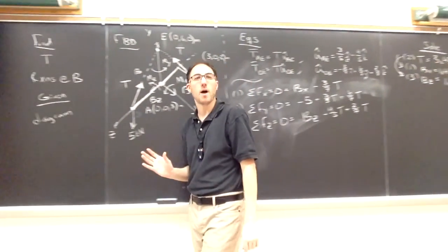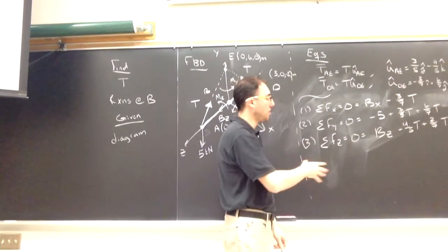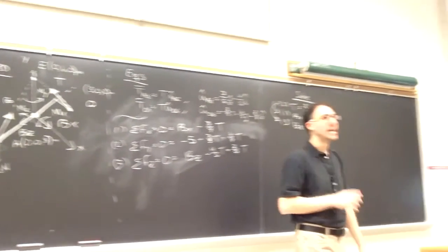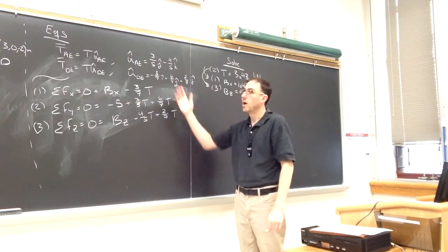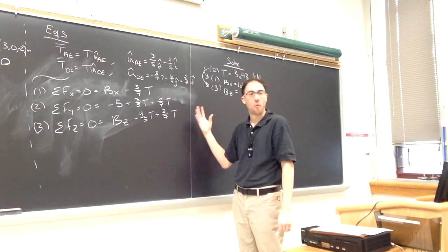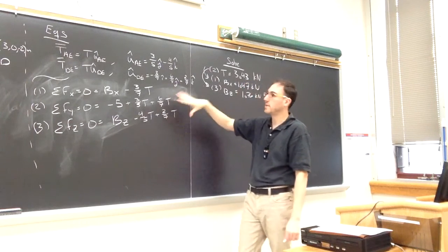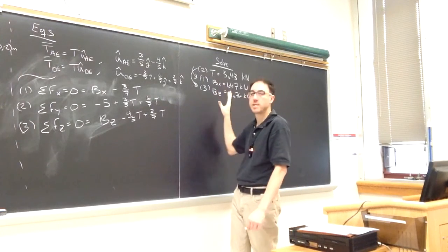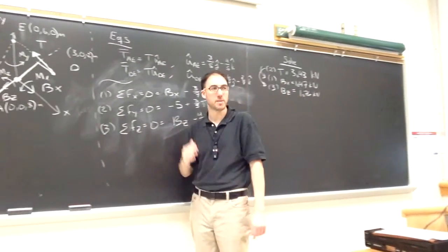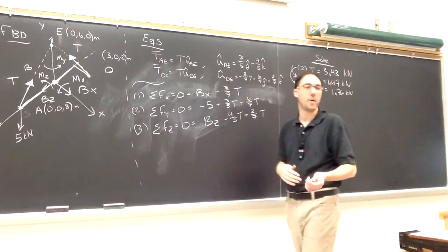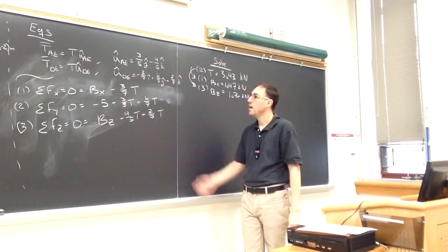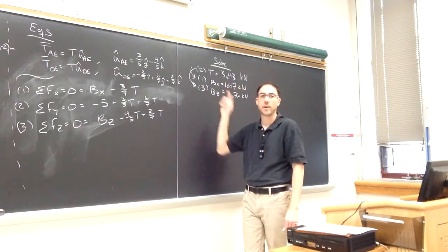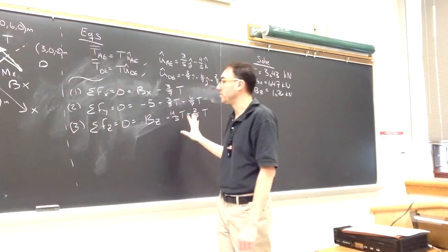For this particular problem, we only had 3 forces, and we were able to solve for all 3 based on the force equations alone. That's not necessarily going to always be the case, because we could have some examples where we have 4 or 5 unknown forces, in which case we might be able to solve for 1, maybe 2 of them, but not all 3. So the solution step could be very different from problem to problem, what you are able to solve right away and what you have to put aside and come back to. So we made 3 equations from the forces. We only had 3 of our unknowns appear in them, and we could solve for all 3. All right, force equations are done.